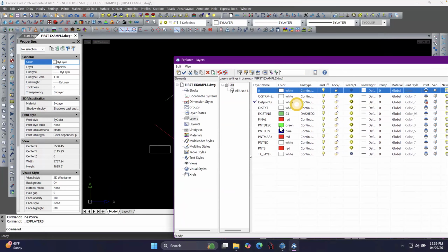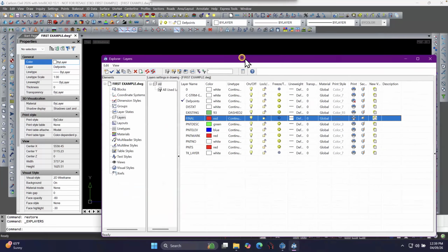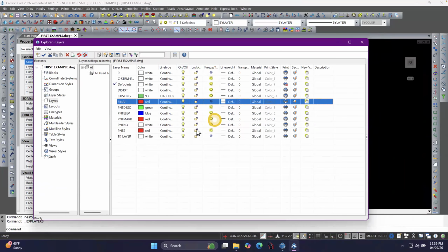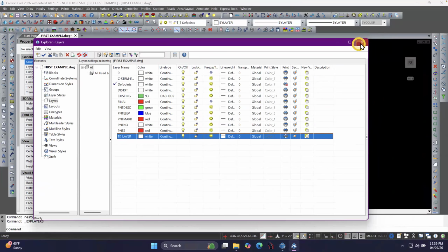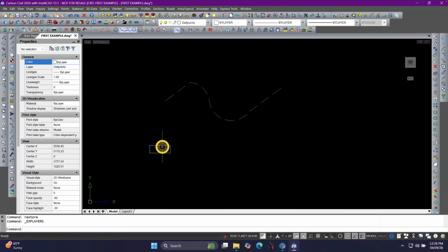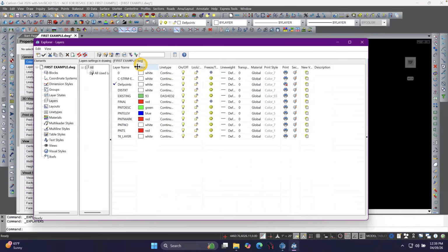And let's freeze that layer final. So I'm just going to click those individually by layers. There's my takeoff layer, which is also frozen, but there's nothing on it. Or yeah, it was other. So you can do that individually, like individually by layer name.